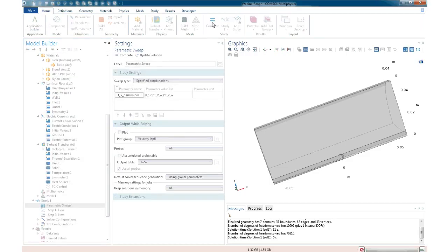So the first point I want to make is the geometry I set up was extremely simple. In fact, if you wanted to, COMSOL would let you take a CT scan of a segmented liver and enter the entire thing in. There are a couple of reasons I don't normally like to do that. The first is, whoever's CT scan that is, your next patient is going to have a different CT scan, so you don't want to build a device just for a single patient.